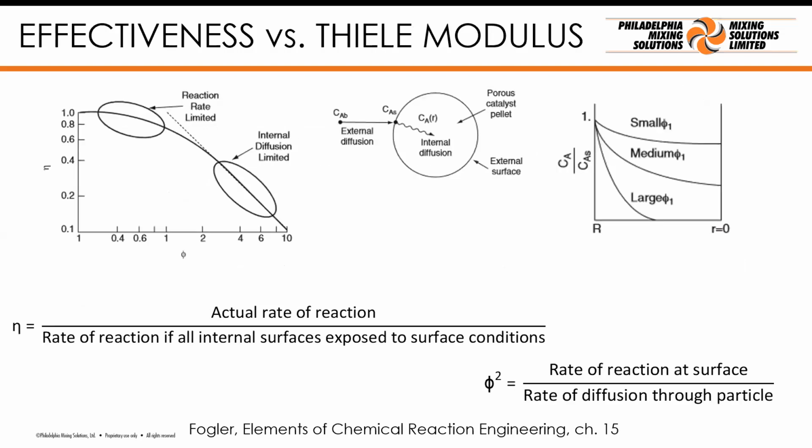And the classic way that this is covered in chemical engineering, reaction engineering, is to look at the Thiele modulus. So when the value is high, we're reaction rate limited. And it says that throughout the pores, the rate of reaction is limiting, diffusion is fast. But generally, we're going to be internal diffusion limited. We're going to be at a lower value.